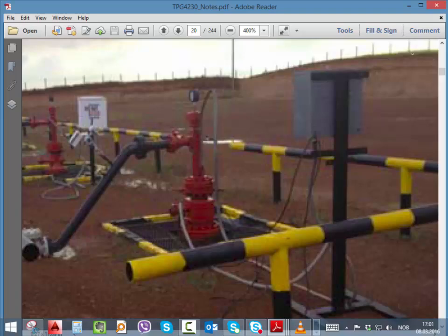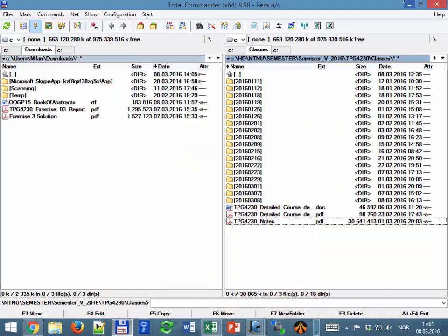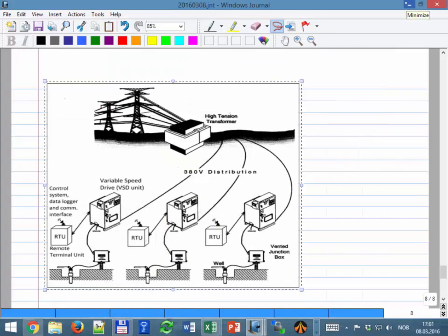Remember, it's very similar to the IPR, but delta P and rate are going down. The reason is that I can get either a high rate with a small delta P, or a small rate but a high delta P. There is some kind of energy conservation. And as I increase the frequency, that curve is amplified, scaling up.